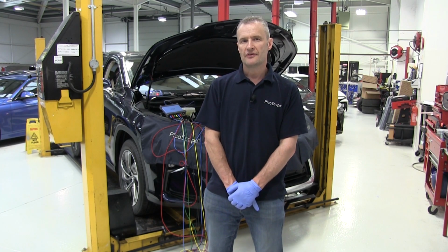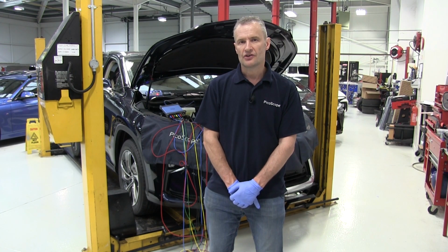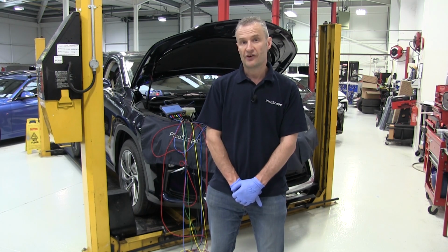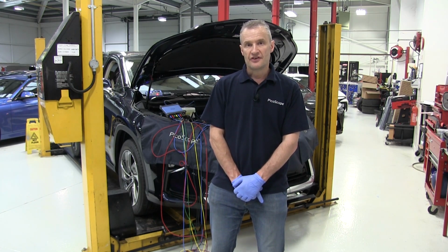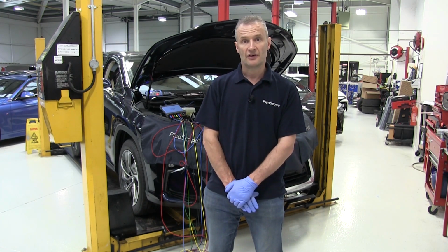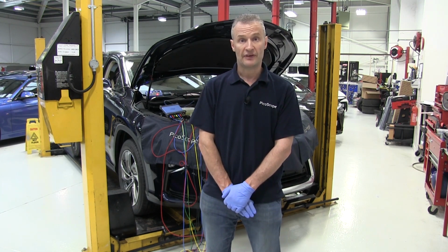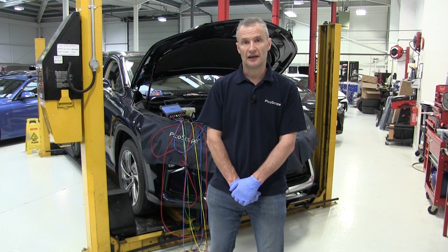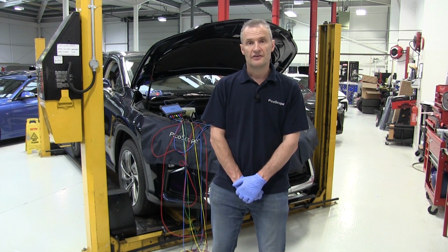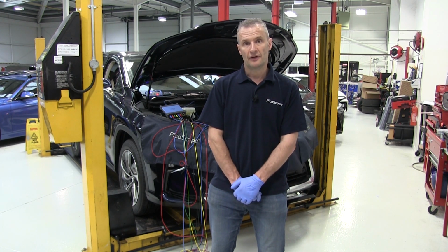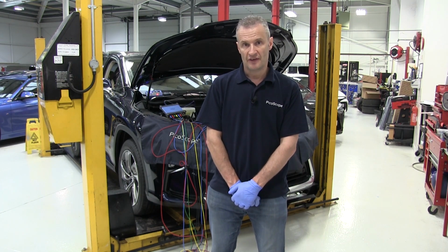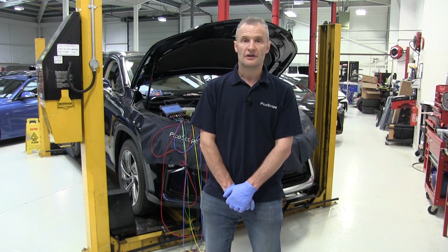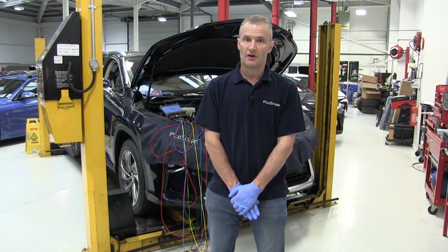One of the key points to remember looking at VVT control and when you're looking at cam crank correlation is to disconnect VVT controllers, however they function, whether that's hydraulic or electrical. On this one we can disconnect each one. It's a simple plug on the front of the controller. We know then that the camshafts return to their default position. And then from there we've got a benchmark to work to.